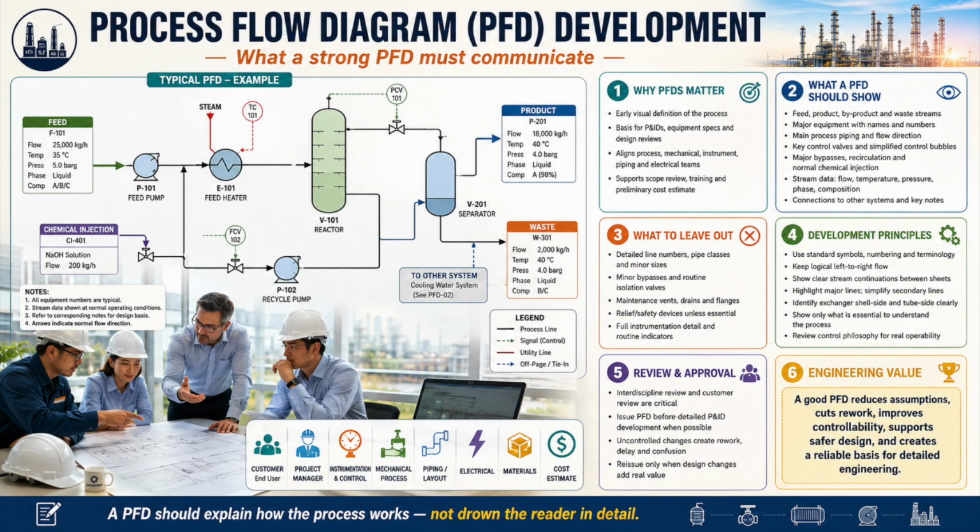A good PFD is also a process optimization tool. Challenge the need for every major equipment item and flow path. Ask why the equipment exists. Ask whether two functions can be combined.